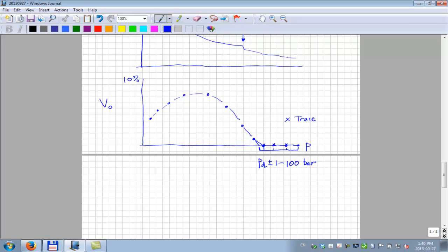They had two laboratories. One laboratory was Core Labs, and the other was the French lab. I don't know if it's Flow Patrol or the Total lab. The same fluid system was sent to both labs. Core Lab came back with a very clear, straight-down dew point of 420 bar. The French laboratory had this tail. It was more than a trace. It showed, but not very much, all the way out to 650 bar. Actually, the Vala was a case where we had a 250 bar difference between one lab and the other.